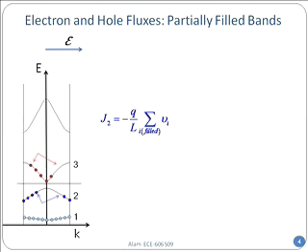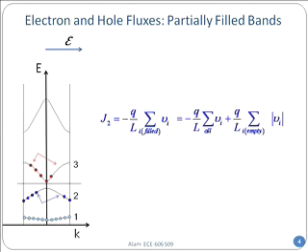How many states do I have per band? Do you remember? This is the total number of atoms that I have in a crystal, right? Now, that could be millions of atoms, let's say, or a billion atoms in a string. So therefore, the number of blue points I have shown is on the order of a billion, let's say, in a one-dimensional chain, although I show here only 5 or 6. Now, if I have a billion, summing them all up to get a current is very difficult. So therefore, I could do the following. Instead of summing over them all, I could partition them.